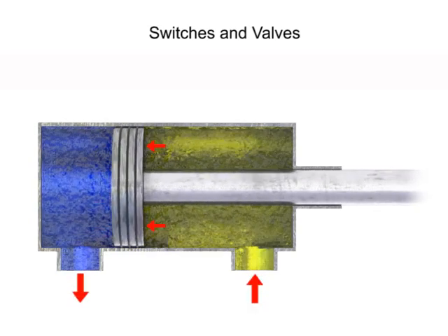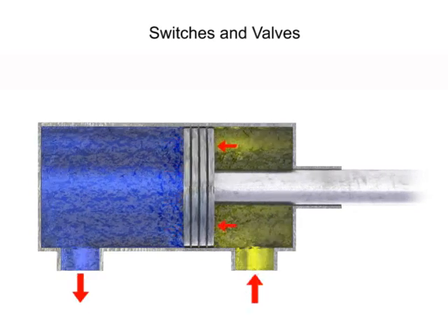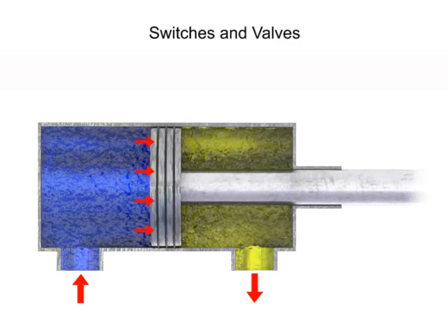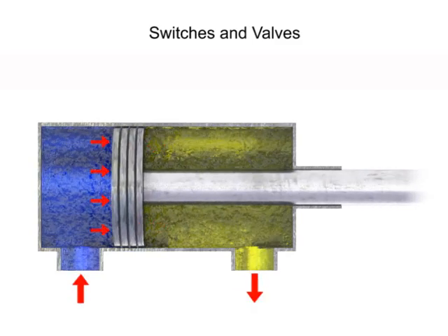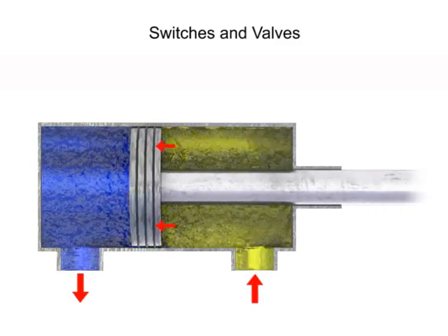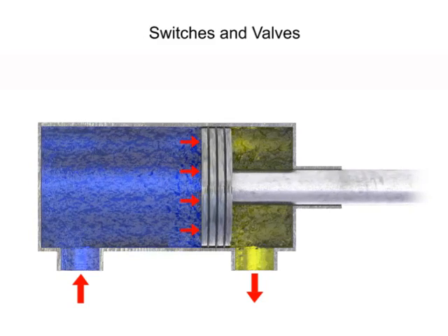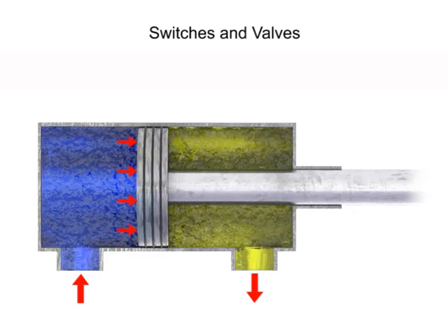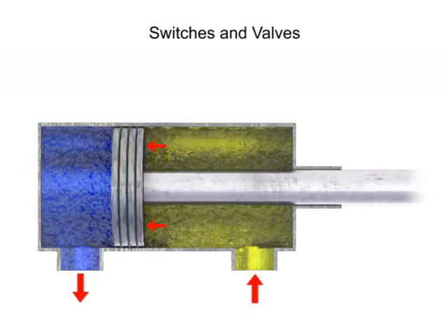In an air cylinder, automatic reciprocation can be stopped by an electrical action or by a shutoff valve in the airline. If stopped by electrical action, it will continue to travel until it reaches one end or the other of its stroke. If stopped by shutting off the air, it can be made to stop anywhere in its stroke.